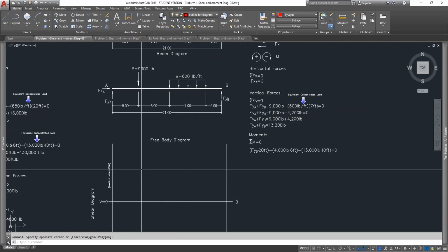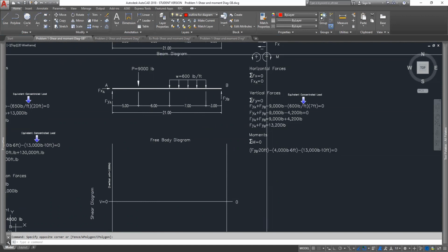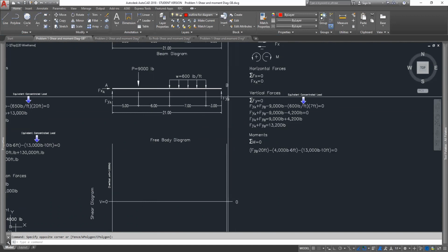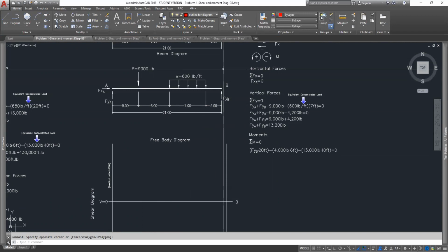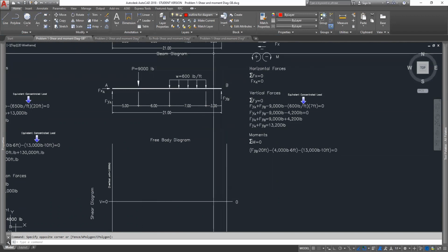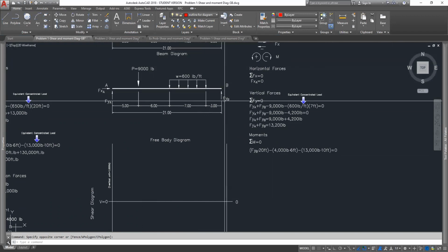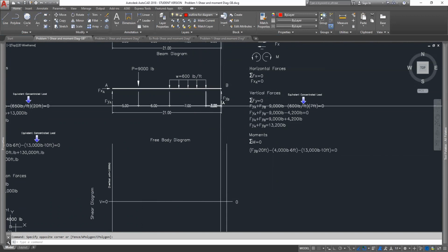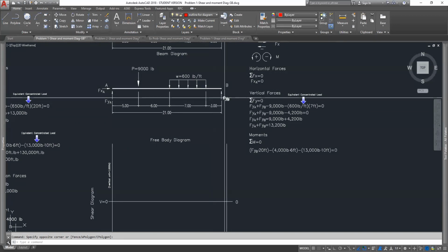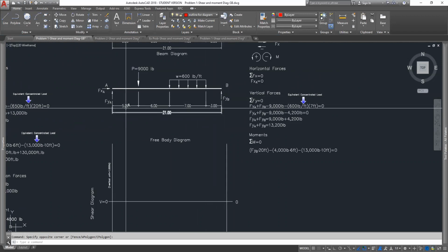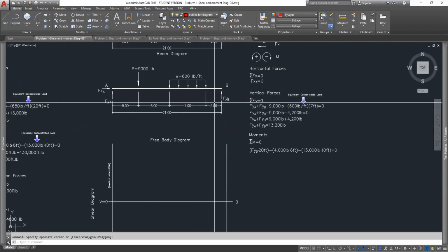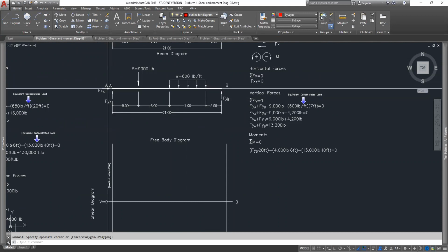It's clockwise. So it's going to be considered a negative moment. The only force we have going up, which wants it to counter that and rotate this way, is our reaction force at the right-hand side. So what we need to do is we need to start calculating the values or the magnitude of these forces times its distance around where you're taking that moment.